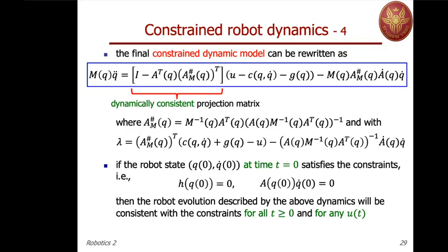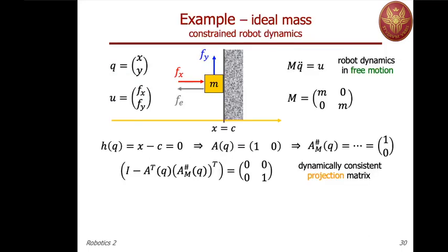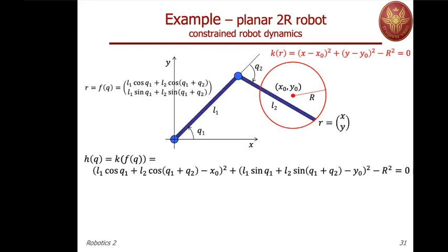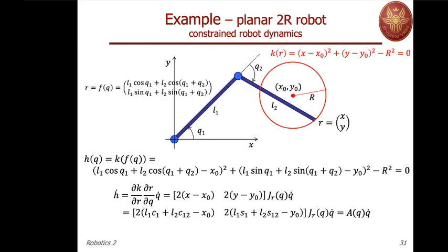But other than that, you have A, and you have A transpose, you have the inertia weighted pseudo-inverse of the A matrix, you have A dot, and then you can really do direct dynamics with this model. So you can simulate the situation for any applied force u. So let's go back to this situation. Okay. So with A, you have everything. This is why I don't proceed farther in the computation.